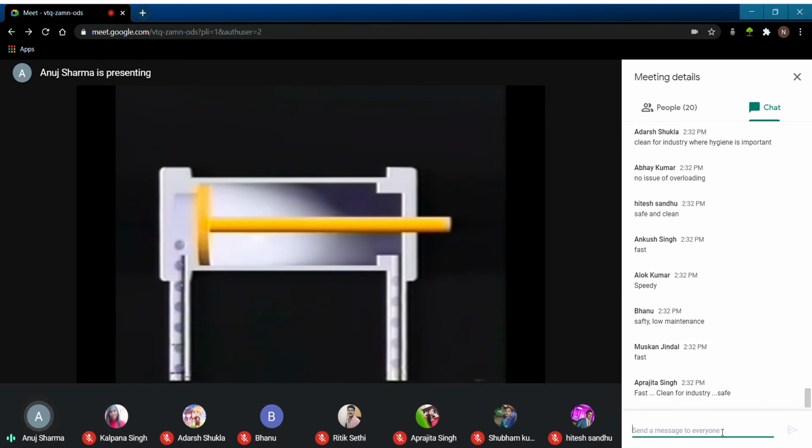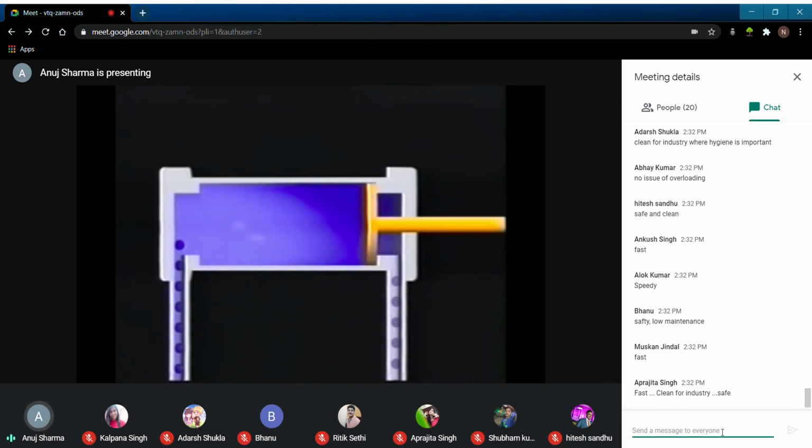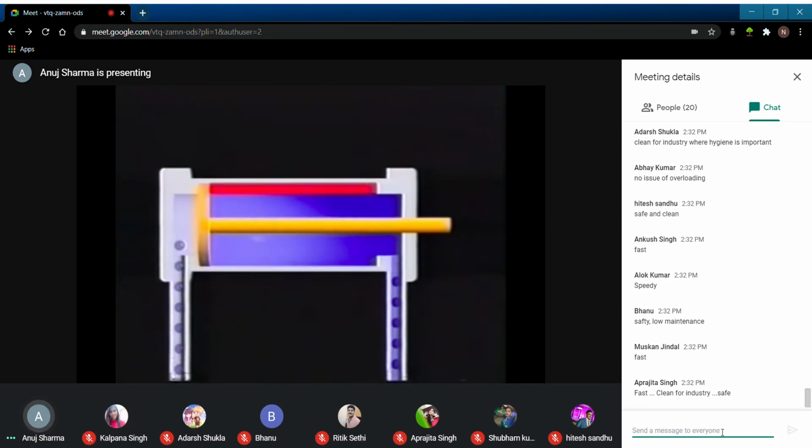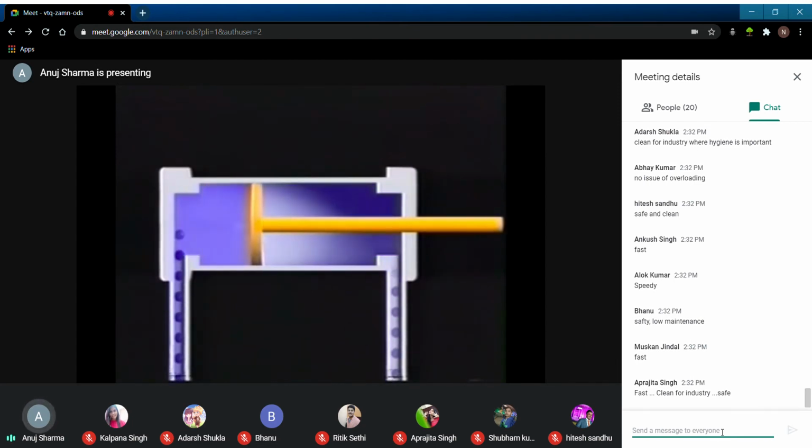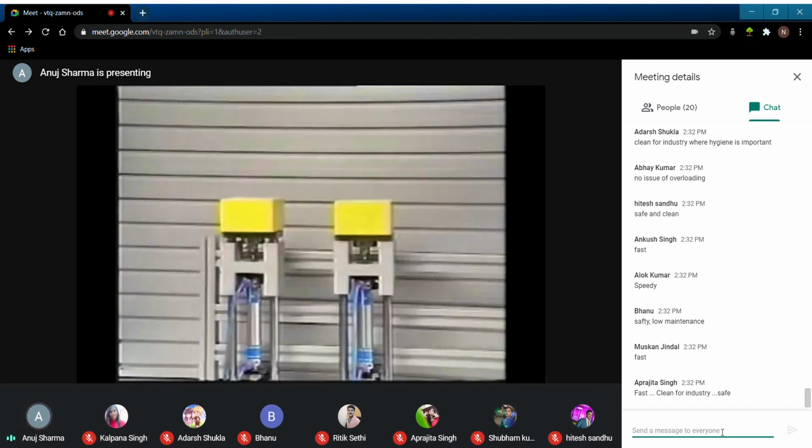When selecting a cylinder for a specific application, you must take various factors into account: stroke length, extension force, and retraction force. And finally, cycle speed. Next, let's examine the relationship between force and speed.